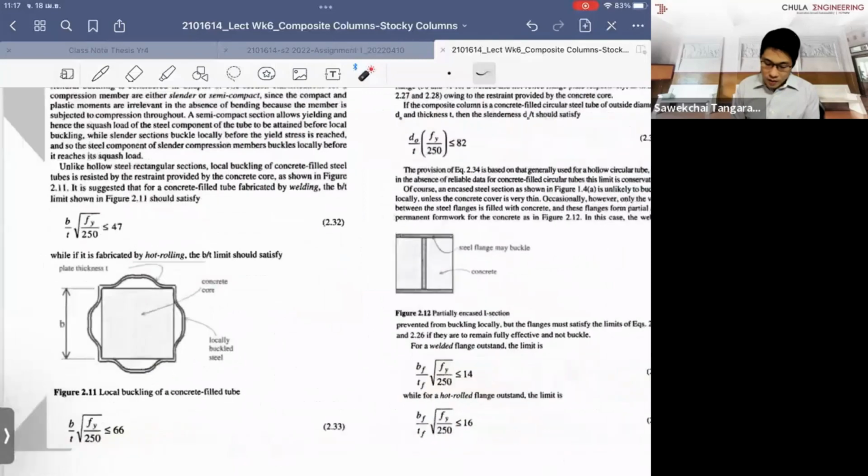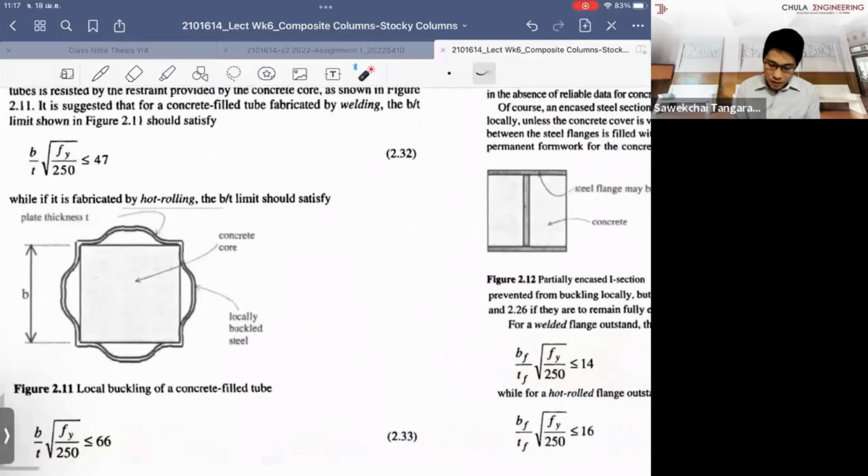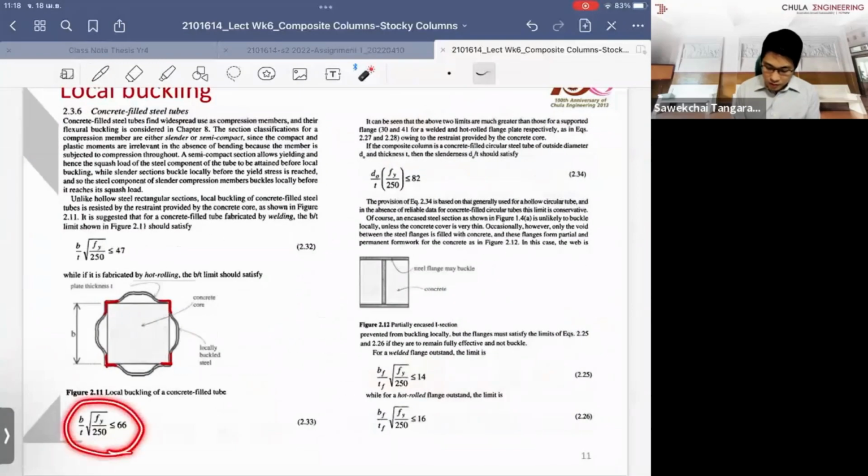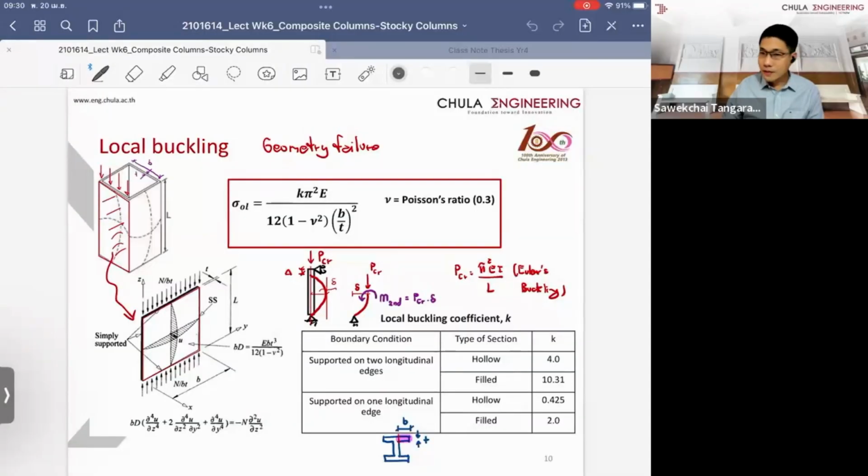And this is how we can adjust this. Remember, we only take into account the effective section. And how we check this, we use this criterion here, right? Last time we discussed what we call the yield strength at the buckling conditions of the thin plate here. And the buckling we discussed is for local buckling only.